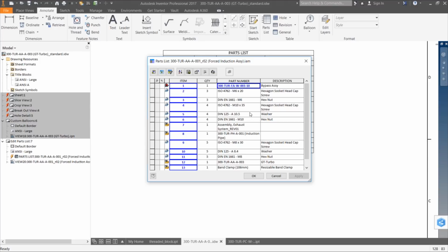That's going to indicate to me that somebody has modified this. So if you're coming into a drawing that somebody else has created and you look in the parts list, you see these bold blue fields, someone came in here and manually overrode the default values. To get back to default, you can simply right click on that value and go down to static value at the bottom of the menu, and you'll see it brings back the default static value.